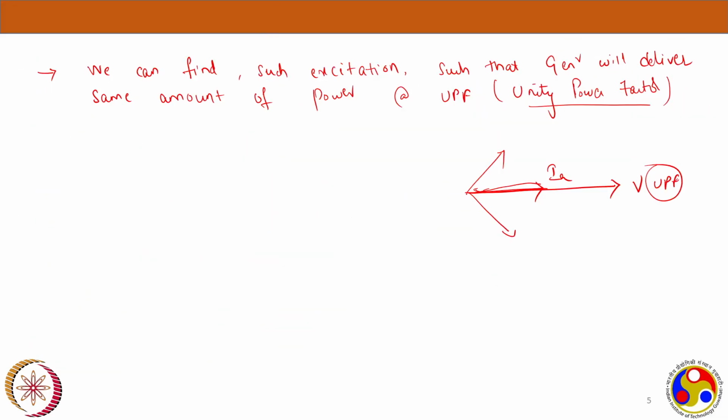So this is very simple. That's how we arrive at the curves of the synchronous generator, where we can see the relation between armature current and field current. This is a very important question: between which quantities will you have the V curve of a synchronous machine? The V curve is nothing but between IA and IF. We will see why it is called a V curve also. But we have understood.